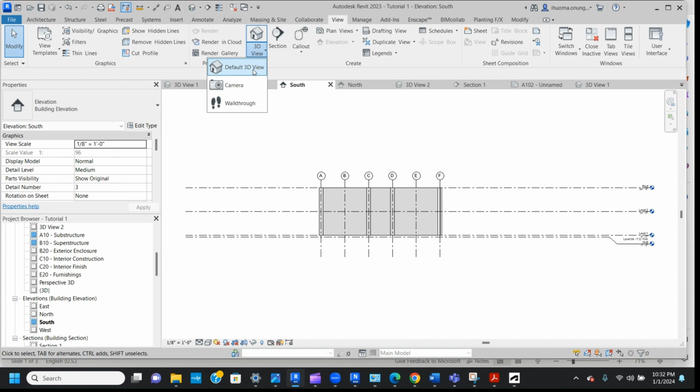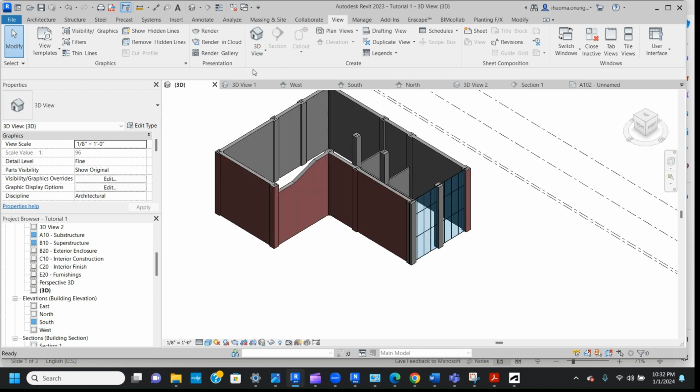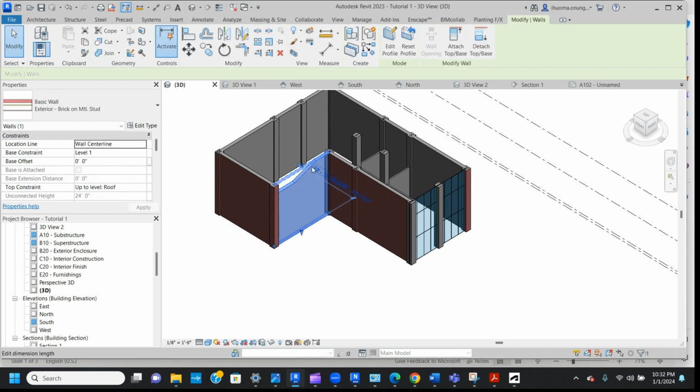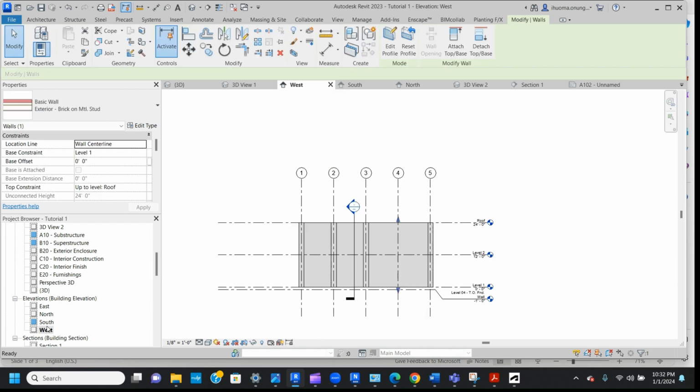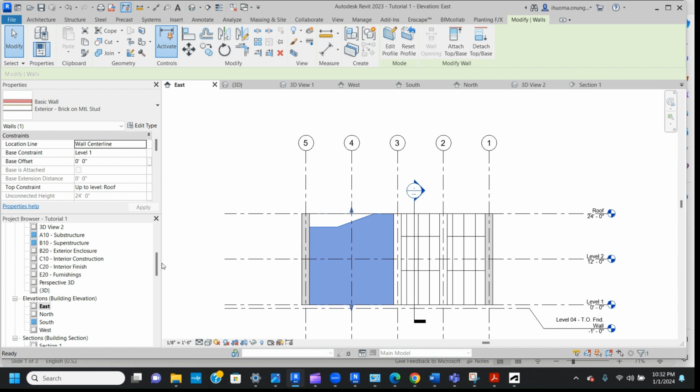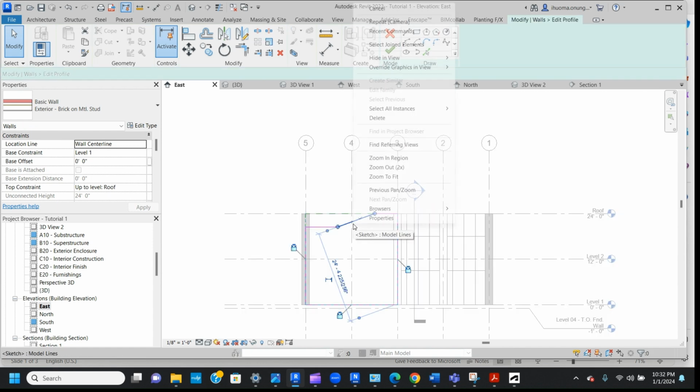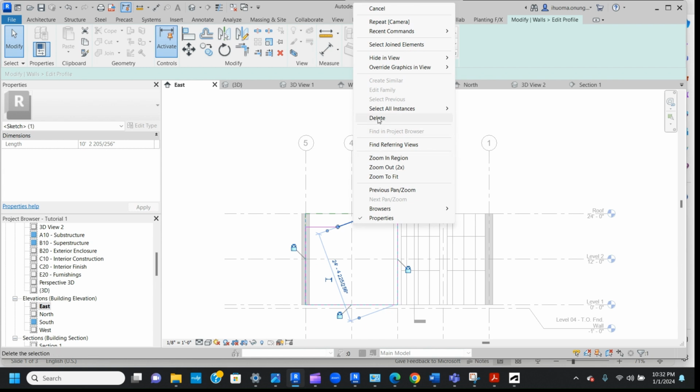We're going to continue our Revit model, the last model that we were working on. So we're going to add floors today. And before we do that, let's convert this and make it a straight profile. So I'm going to do that in the elevation view. I will edit the profile and make it straight again.